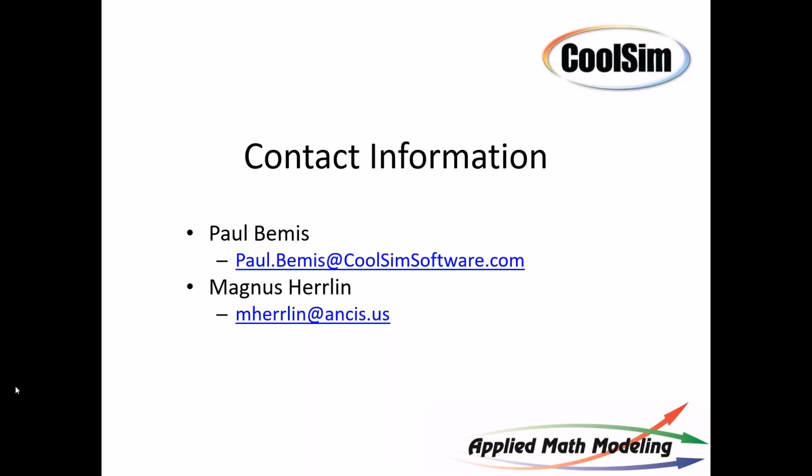Direct free cooling with a proper filter could also reduce PUE dramatically, of course. Yeah, direct free cooling is always with proper filters. Yes, you are right, Audrey. But I have also been in data centers where it has rained because they're using free cooling. That was at a Princeton data center, where the original design was fine, but it got out of whack over time, and the people who designed it went away.